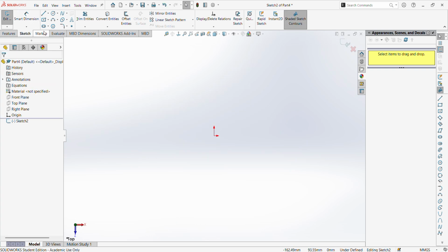And here's a rule of thumb, or a little tip you could do. You could open 4 separate parts, right? You can make a little folder on your desktop that's called SolidWorks. You could start the part, select the measurement, save each one of those parts, and label them in the filing system with what dimension it is. That way you open the part, make it, then just rename it. You already know you're in that dimension because you opened that part. You rename it to the part you're going to build, and then put the part where it belongs in your file system. So that's a little tip.